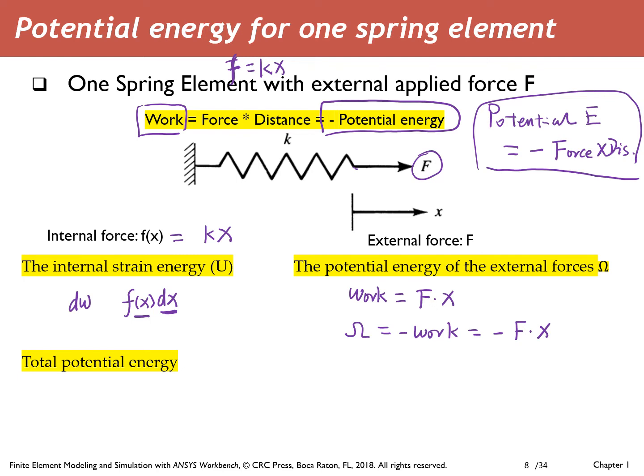Then the total work in terms of calculus is the integration of the small work because of small deformation, integrated from zero to the final deformation. The work is done from 0 to x by the internal force, and we also note that although the magnitude is kx, the internal force in the spring goes in this direction.